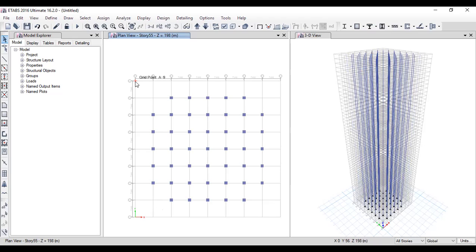So these are the interior columns. Edge columns are here. We will draw them when the slab is rotated, okay? Because those columns are rotated with the slab, not these interior columns, right? The interior columns remain the same, while the slab with these edge columns will be rotated. So you need to draw the shear wall. I'll take the center and select these columns as well, and then delete.